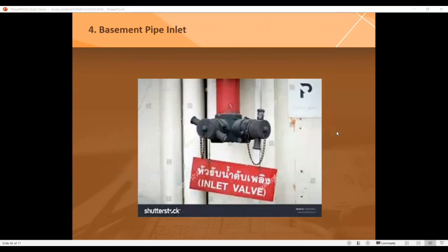Basement pipe inlets shall be installed in the first floor of every store, warehouse, or factory where there are cellars or basements under same, except where in such cellars or basements there is installed a fire extinguishing system as specified in the code, or where such cellars or basements are used for banking purposes, safe deposit vaults, or similar uses. Next is material.